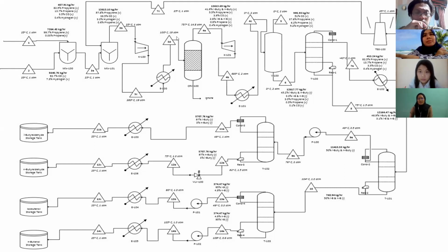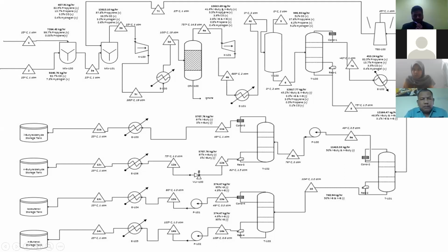Okay, sir. The gas outlet stream of this reactor consists of side products and also main products. The side products are isobutanol and butanol, and propylene, carbon monoxide, hydrogen, and propane. As we see, four components have negative boiling points, which are propylene, propane, carbon monoxide, and hydrogen. So if we set the temperature at 0 degrees Celsius, that temperature is perfect to separate the vapor stream, which is propylene, carbon monoxide, propane, and hydrogen, from the liquid stream, which are our products: isobutyraldehyde, n-butyraldehyde, isobutanol, and n-butanol.